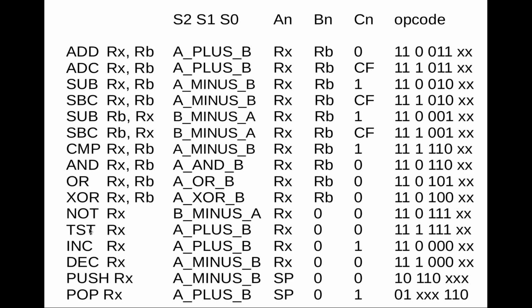So we can define such an operation by redefining a NOT with carry as in fact a test. Just as in the case of the compare instruction, all we want to do is set a series of flags. We can achieve that by adding together the original register with a 0. The result of that will be the original register. And if we also set the carry in to 0, then we really will get the value of that original register. The flags will reflect whatever is in that register, whether it's 0 or negative, etc.